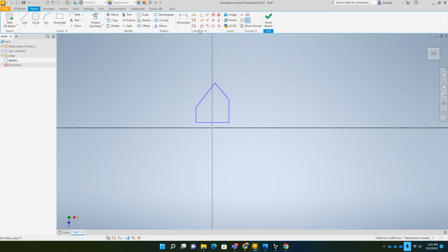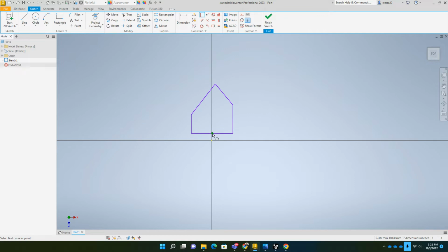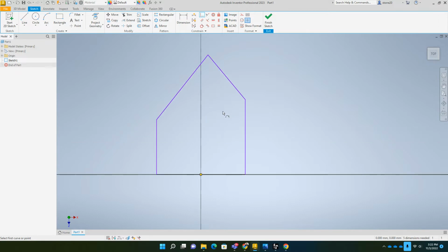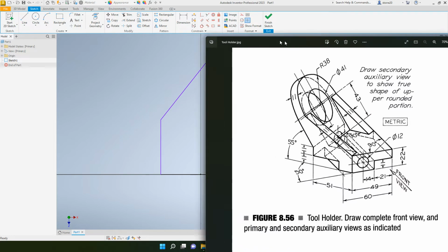And we always start with our geometry. I'm going to start with a coincident constraint here. I'm going to probably pick the midpoint. It doesn't have to be, but I do use the midpoint a lot in sketches and geometric planes. So it's a personal preference. So I'm going to do a coincident constraint of that midpoint to the point right there. 5 dimensions. So I think geometrically, this is a real simple shape. It should keep the shape that I need. It's really just going to be those dimensions that I was talking about.